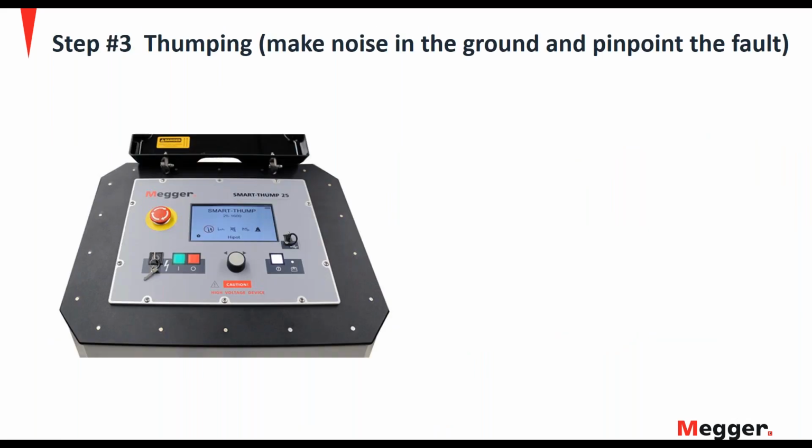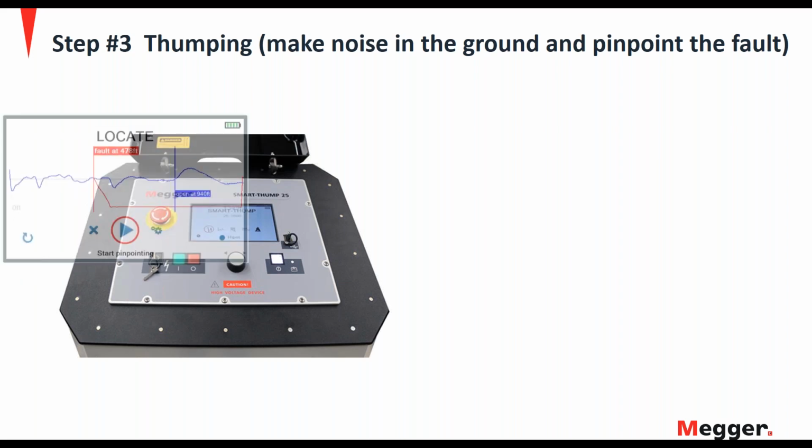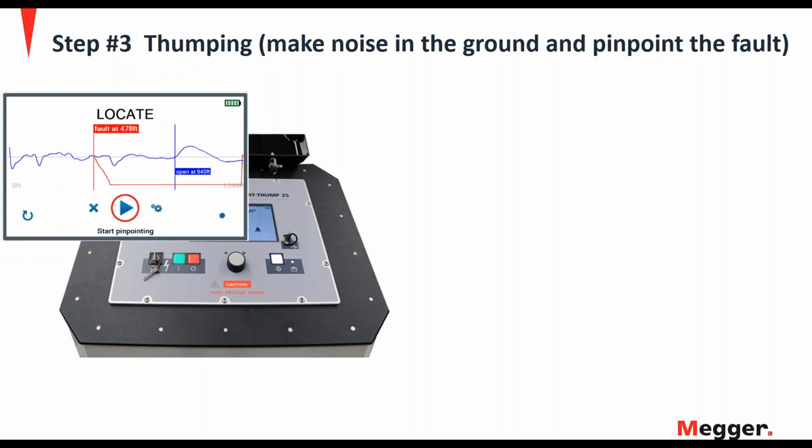Okay, so step 3, thumping, make noise in the ground. We finish here, have our distances. We have a distance to the end of the cable, and more importantly, we have a fault distance. Now we're ready to go pinpoint that fault.